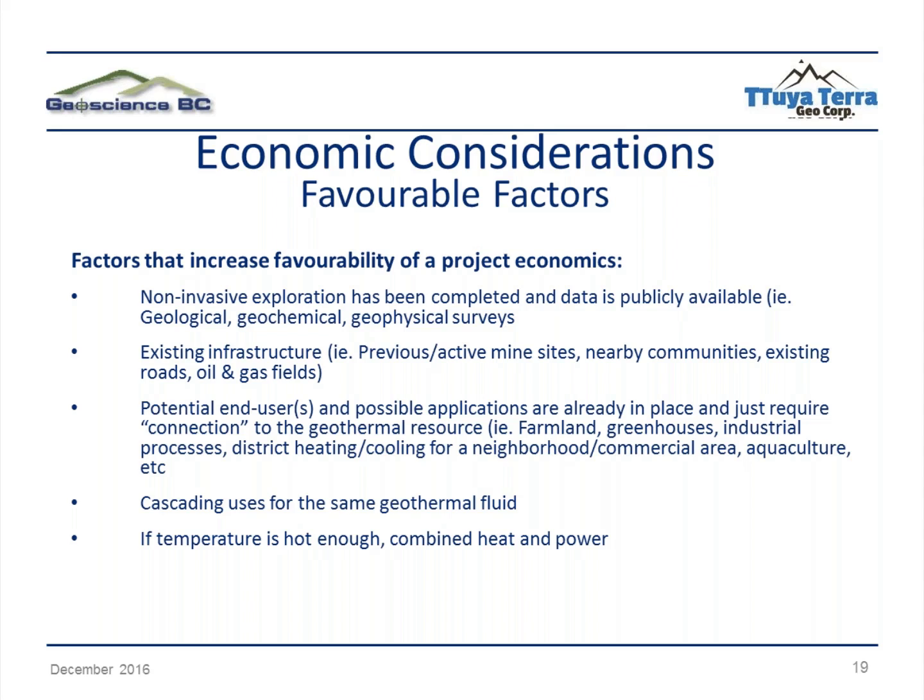And again, just hitting home the cascading uses for that same geothermal fluid. At the higher temperature, you could be using it for end-use applications that need that temperature. But as the fluid is going through that process and some of that heat is extracted, at that lower temperature stage, you could still be using that fluid for another process that doesn't require as high a temperature, and so on. This cascading use for the same geothermal fluid is really key for increasing the favorability of project economics.